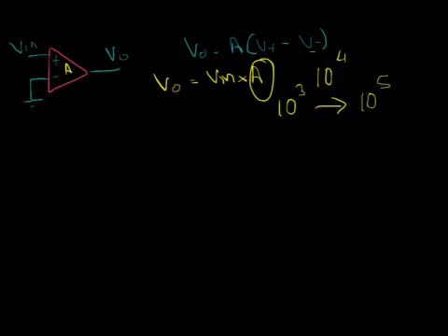So if say Vin is 2, so instead of 2 into 10 raised to 4, the Vout can go from like 2 into 10 raised to 3 to 2 into 10 raised to 5. Also, these are very high voltages and we almost never want to work with such high voltages. And even if you try to reduce A, like say if you want an A of 2, getting exactly 2 is next to impossible. It can go anywhere from 0.5 to like 5.